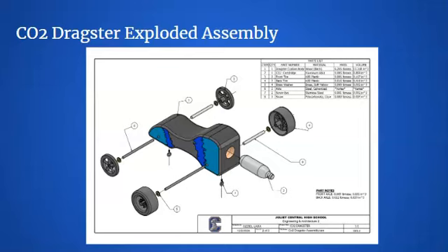During the making of the explicit assembly, I noticed that my front axles and back axles were labeled the same in the parts list, which is located at the top right corner, and labeled the same when I ballooned the parts. I came to the realization that this occurred because, during the making of the two different axles, I made a copy of the back axles to use as a basis for the front axle model.